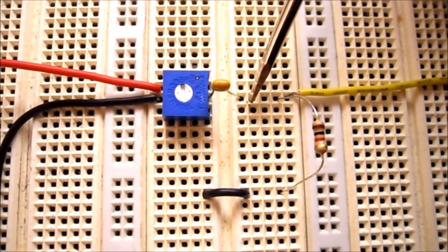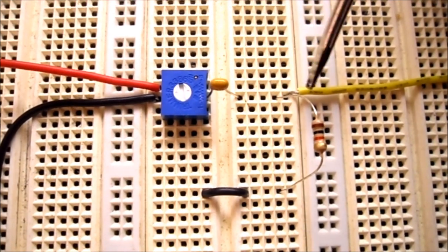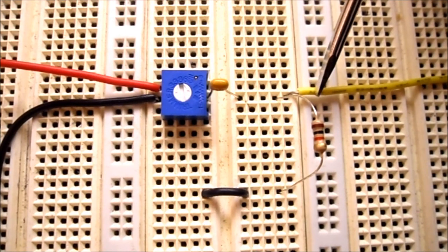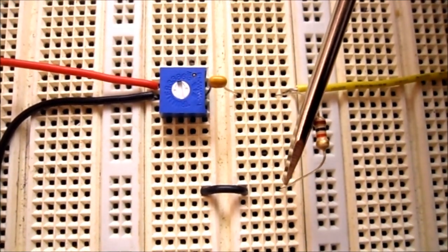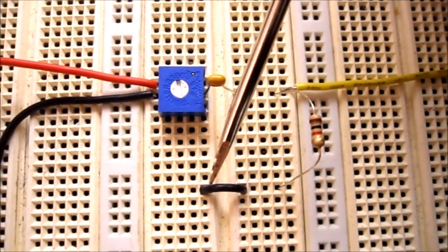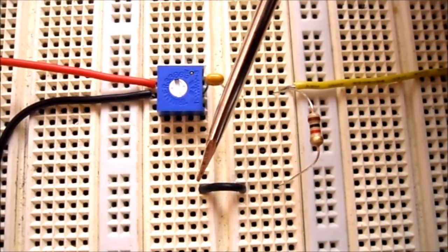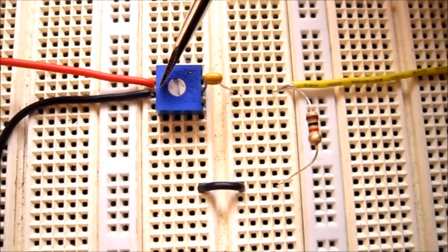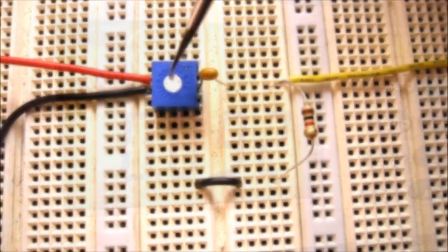The capacitor is connected to my load resistor, and the output sensing wire that goes to channel 2 of the oscilloscope. The bottom of my 1K ohm load resistor goes to this black wire that will go back to the common of the function generator, but for right now all I'm going to do is measure the resistance and adjust my potentiometer.